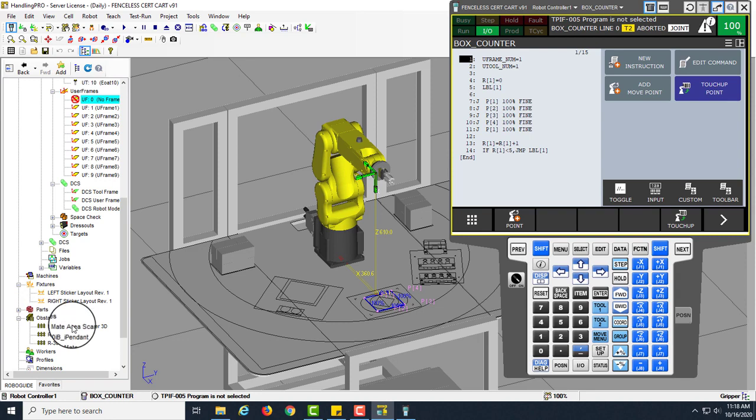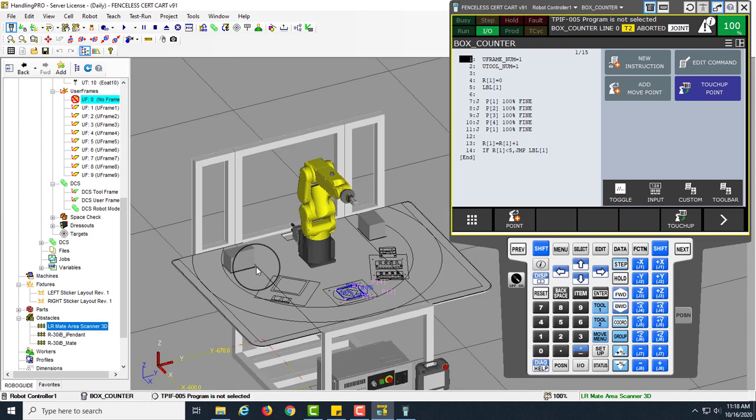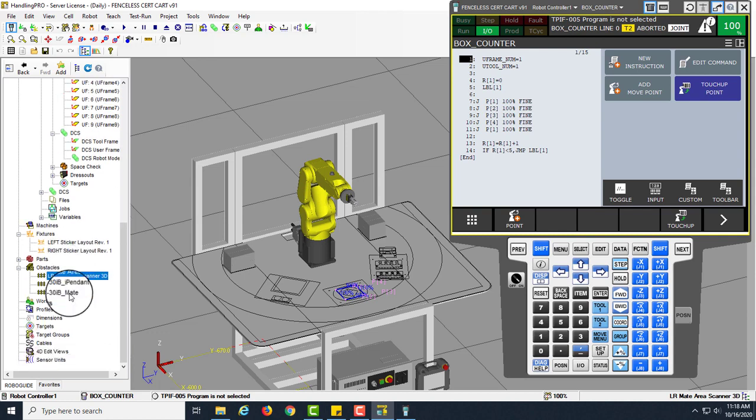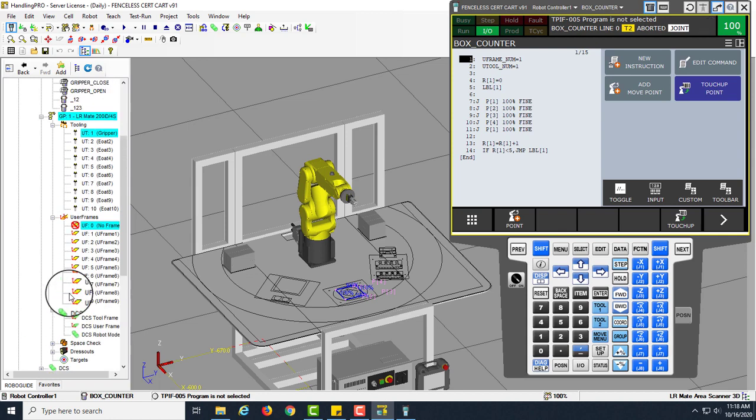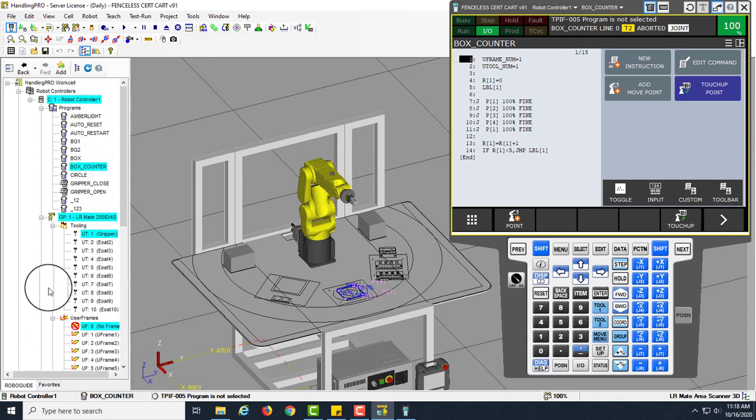For example, the main obstacle that we have with our robot is the robot cart itself. You can see that's attached and it's highlighted. And then this is really where a lot of engineers do a lot of their programming, in the cell browser. But I like to always start out, we can teach all the same stuff using this digital teach pendant right here.